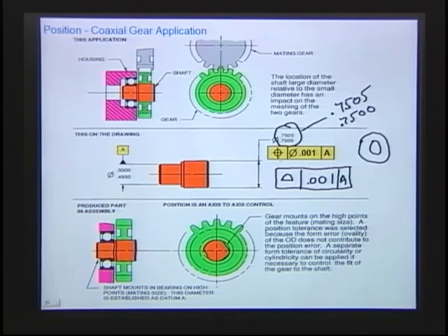And this would not be appropriate for runout. The reason it wouldn't be appropriate here for runout is because if I put the indicator on and this thing was oval, the needle starts moving, and then I couldn't be as much off center. So to me, this here is a position call-out. I would use only position on something like that. Runout would not be appropriate there.